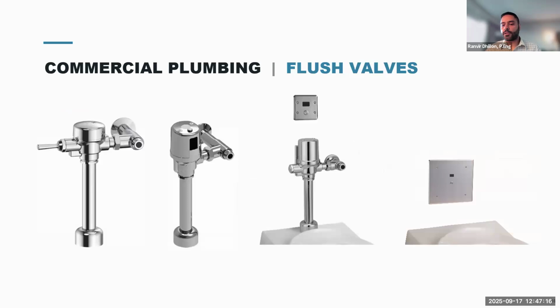A flush valve uses water pressure directly from the water line connecting to it to flush the water closet. Because of that, flush valves are typically selected for commercial facilities where multiple fixtures would be activating simultaneously. Each of the flush valves has minimum incoming pressure requirements based on the manufacturer's specification, which you need to take into account when designing the water system for the facility. One of the major benefits of this system in a commercial building is that unlike a residential toilet, the user doesn't have to wait for the tank to fill up before flushing. So that reduces the refill time. Also, flush valves mix air and water to achieve more pressure while flushing, so they can provide a cleaner water closet bowl.